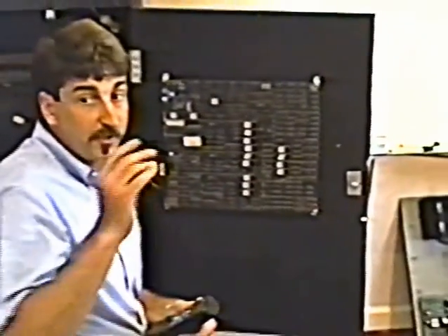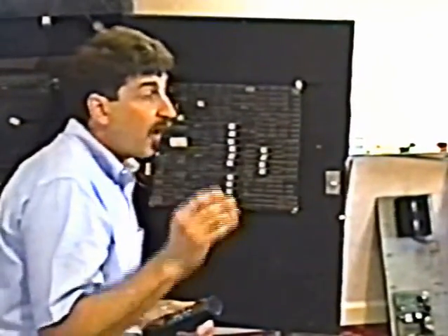When you go to put this guy in, you've got to be very, very careful that you don't bend a pin. If you've never done this before, if you've never pulled a chip out before, don't even try this on a board you ever expect to work again in your life.